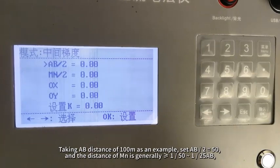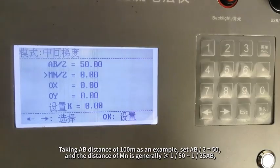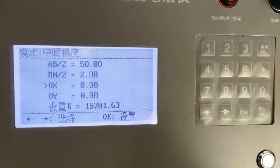Taking AB distance of 100 m as an example, set AB/2 equals 50. And the distance of MN is generally 1/50 to 1/25 of AB. Take MN as 1/25 of AB and calculate MN/2 equals 2.